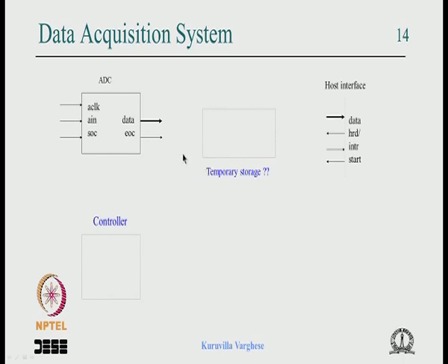That means when it is empty you do not read, when it is full you do not write and so on, okay. But that is a FIFO. So the FIFO is the best solution in this case. So let us try to put it, and you know that the controller gets a clock and a reset.